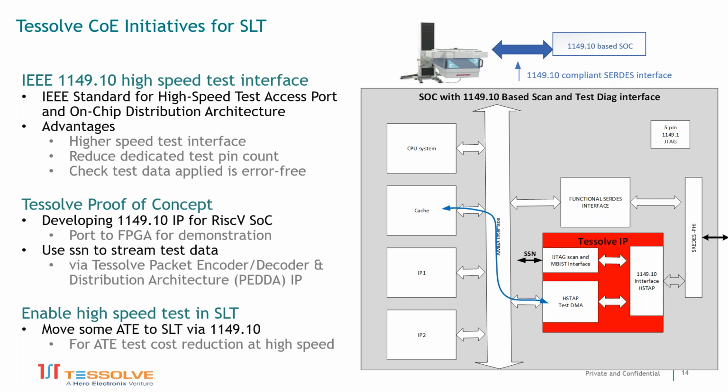And one other important thing which I should mention, but that doesn't really come out very well on the slide, is the repair as well, because what you don't want to do is have 17 chiplets and one of them fails and you throw it away. What you want to be able to do is to see if you can repair that chiplet in some way.